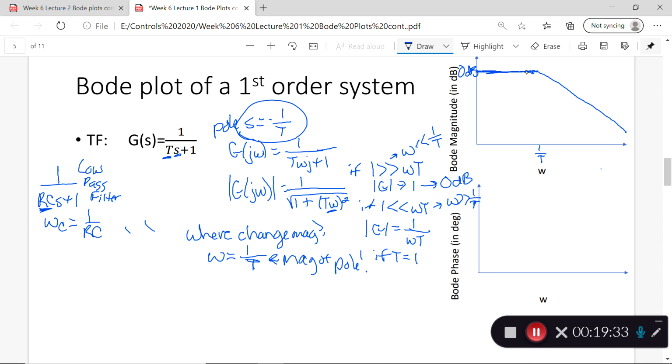And that cutoff frequency was where, when we graphed on a log-log scale, omega again being our frequency and our y-axis in decibels, it went from basically being flat to curving down. And what slope will it be curving down with? I have one pole, no zeros, so at negative 20 decibels per decade. Cool. What about phase? Phase is a little more complicated.